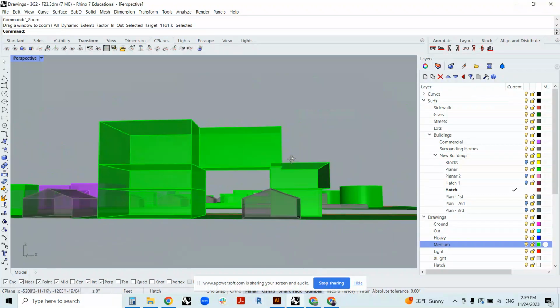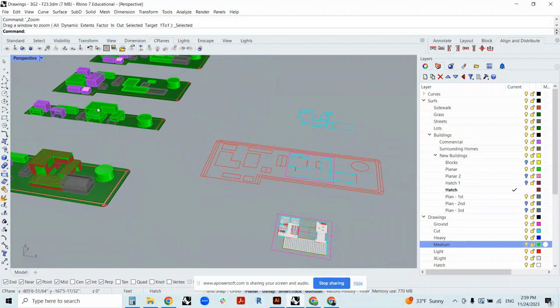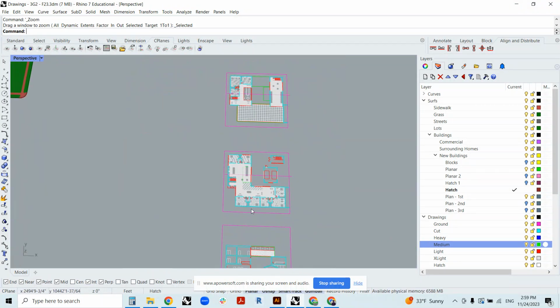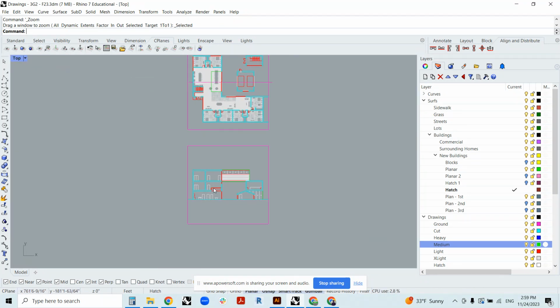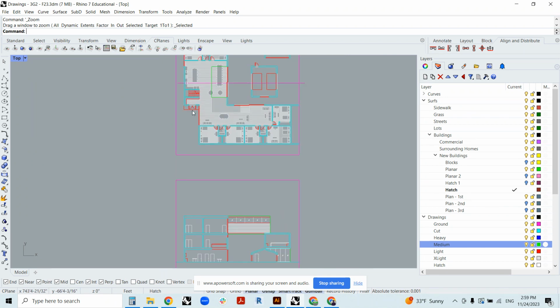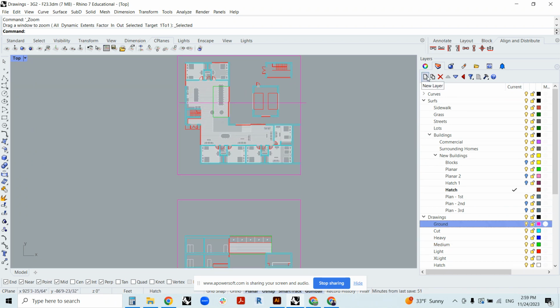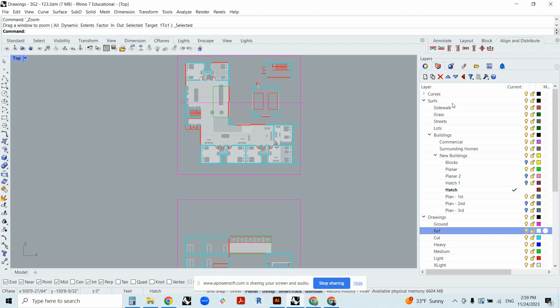Again, if this helps you visualize what you're cutting through, that's fine. Then you can do your make 2D, and then you start adding in thicknesses. Align it with your plan. You can use the plan to align various elements in the plan.